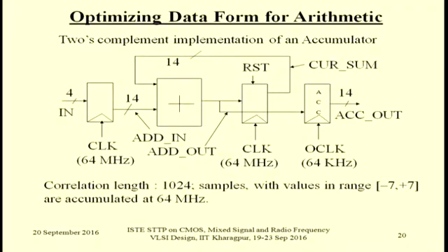Okay, so that means 10 more bits are required. 4-bit numbers, it can be positive or negative, and 10 bits for overflow. So this accumulator should be a 14-bit accumulator. Okay, and we have got an output register. This is the final accumulator register, and this is the adder. Adder should be 14 bits.